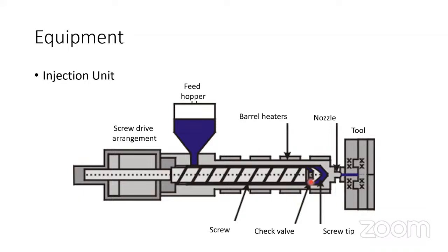Here all the plastic granules convert into a liquid flow, into the liquid, molten mass. Here in compression, the granules are softened. They are converted from solid to liquid, where in the compression section pressure is applied. And that's why the name is compression section.